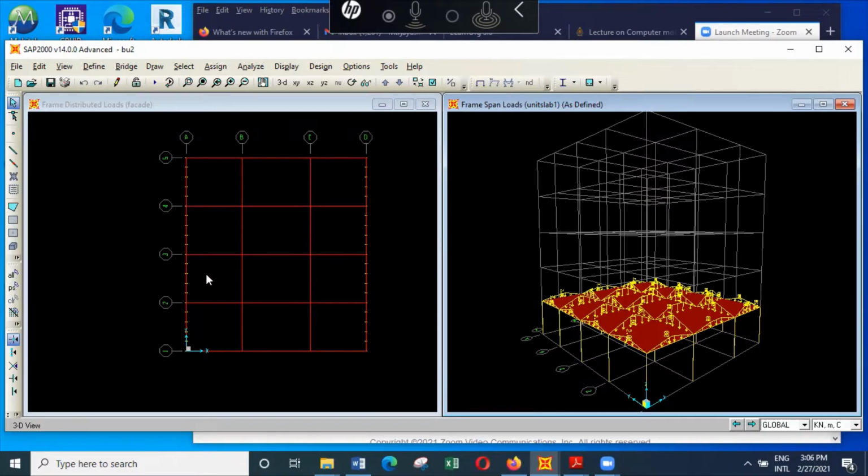So we'll consider wind load also acting on the same structure, and for this problem we'll consider the magnitude of the wind load to be 1 kilonewton per meter squared of the facade area. And generally, when you do the calculation at a height of around 5 floors, you'll get about 1 kilonewton per meter squared. So I will consider that particular wind load is effective at all floors.